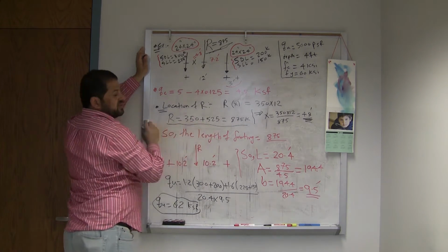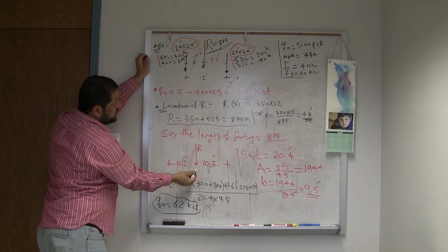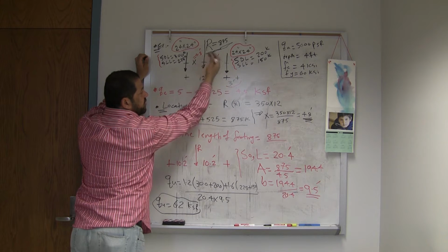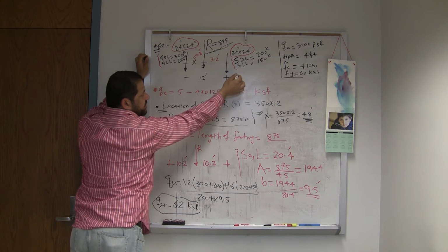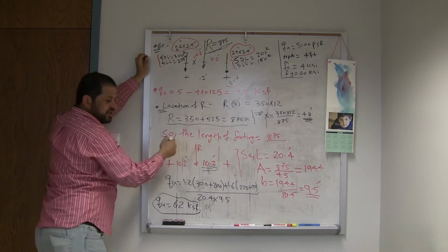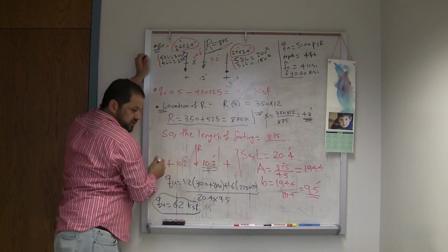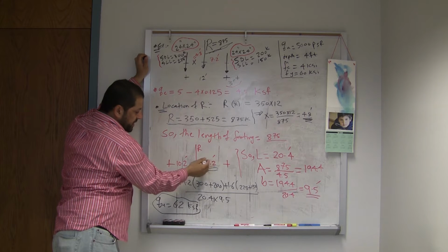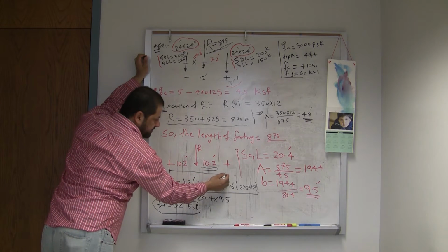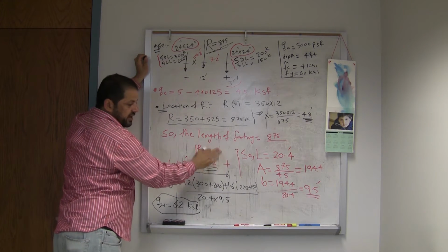So how much is the length of the footing now? Look, this is R here. So we have 7.2 and 3. That's the maximum I can go from one side. 7.2 plus 3, so that's 10.2. And this footing must be centered about R, so it must have the same length on both sides of R. So if this is 10.2, this must be 10.2. And this tells us the length of the footing that we are designing, which is 20.4. So we have 20.4. We are limited with that.